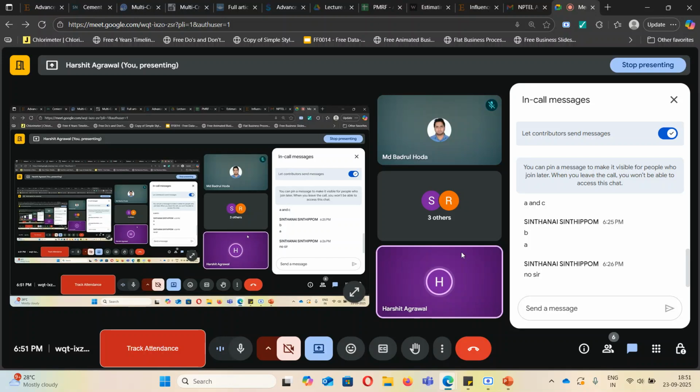Then we need to determine whether it is a sway frame or a non-sway frame, for which we need to calculate the stability factor. In the stability factor, we need to know the lateral flexibility of the column. So we'll calculate the flexibility of column as summation of displacement of columns and displacement of girders. For this we need to calculate the net moment of inertia of column and net moment of inertia of beam.